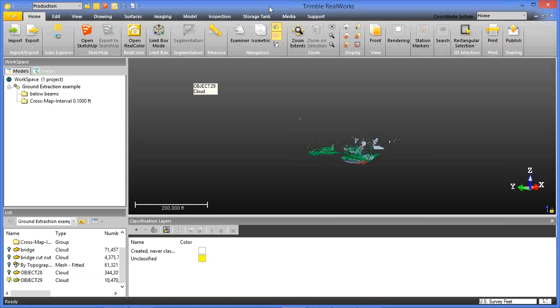They've also added here a new classification layer. So this is considered a window, much like your workspace window, your list window. Now you have a classification layer window, and this pertains to import or export of certain third-party file formats. That would be your .pod for Bentley, LAS or LAZ files for common exchange file formats. They support classification, so that when you segment certain parts of your 3D laser scan, it's going to maintain those classifications for easy data management.